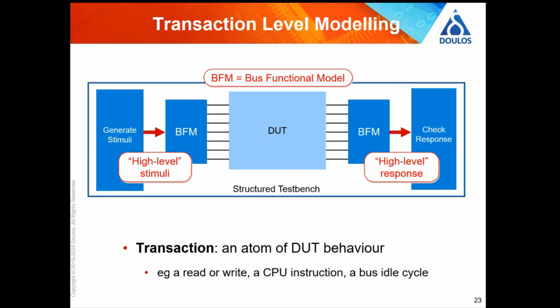Obviously, we need to represent this high-level abstract thing in some way. And we're going to start by calling what are called tasks in Verilog. In VHDL, they're called procedures. So if you know VHDL, not Verilog, it's the same thing. And obviously the DUT doesn't understand that. And so we need a component, a piece of our test bench that translates between this abstract software-y thing called a transaction and the actual ones and zeros that the DUT understands.